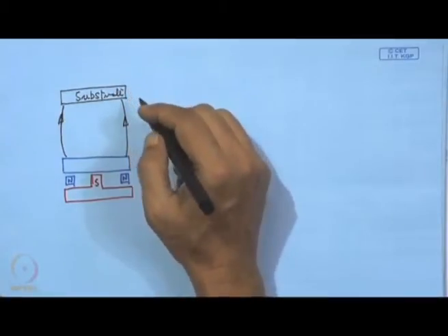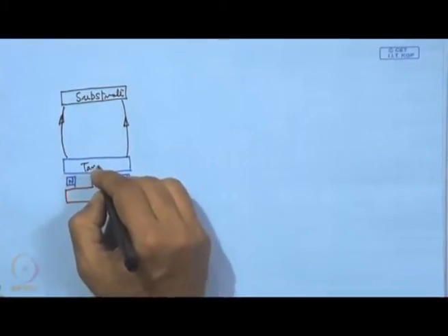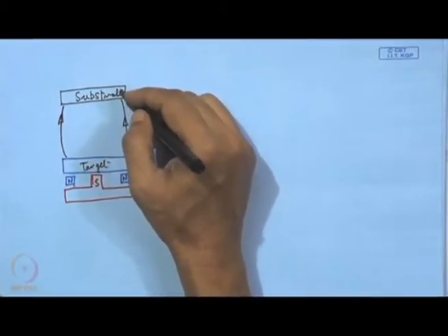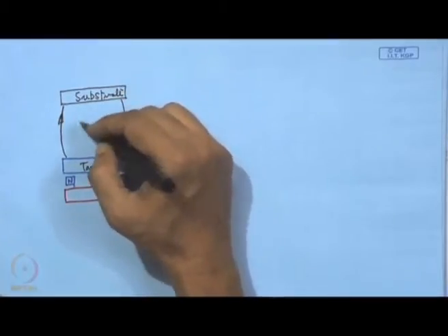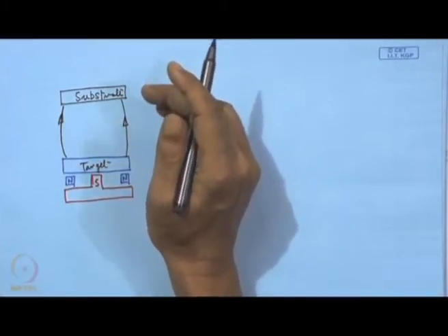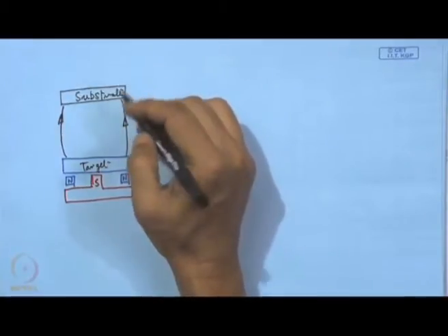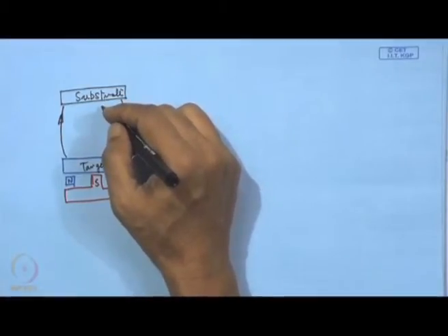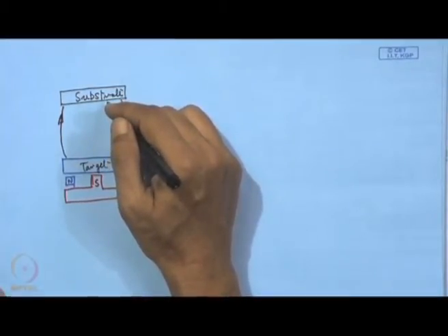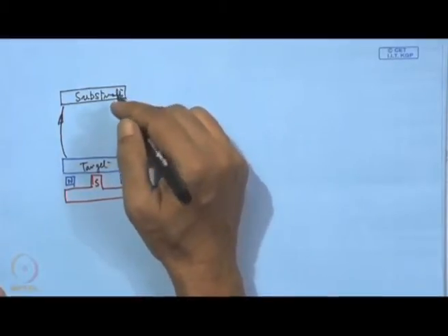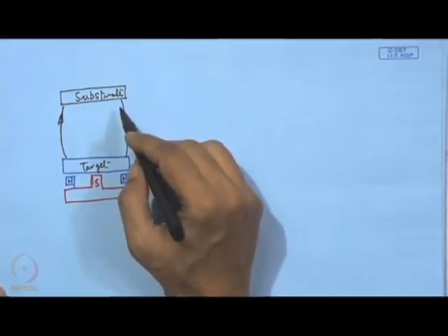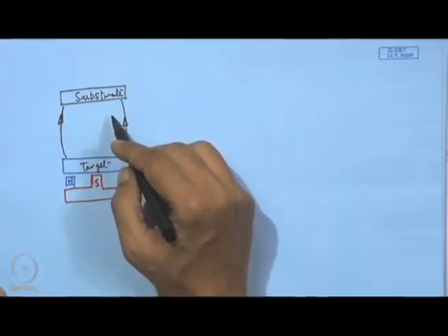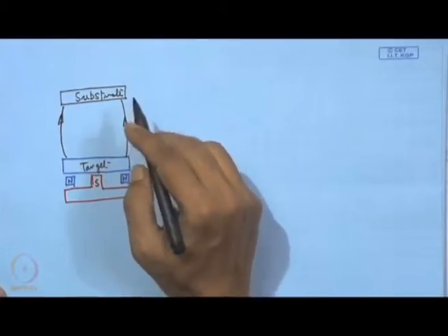So, when we have a substrate with a complex geometry, suppose this substrate has a cylindrical shape or some 3-dimensional geometry, in that case covering the substrate with the same uniformity of the coating thickness, that is issue number 1, and also having uniformity of the property of the coating over the entire surface, that is actually one difficult task.